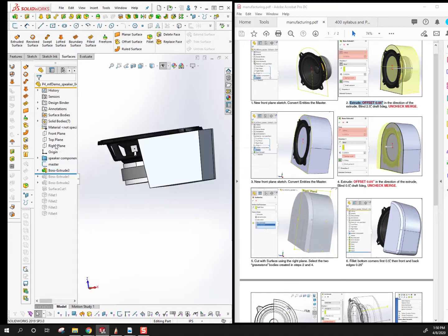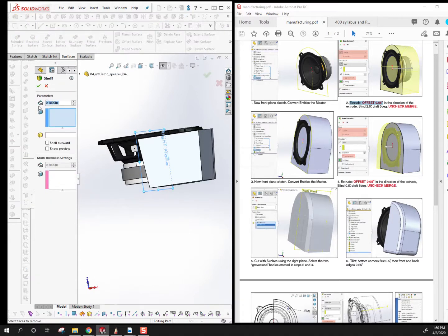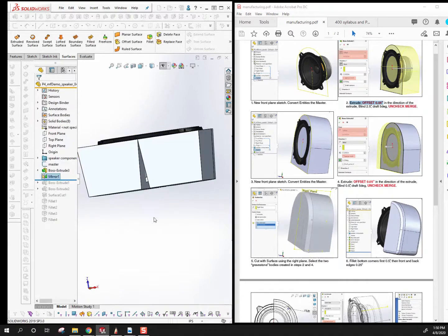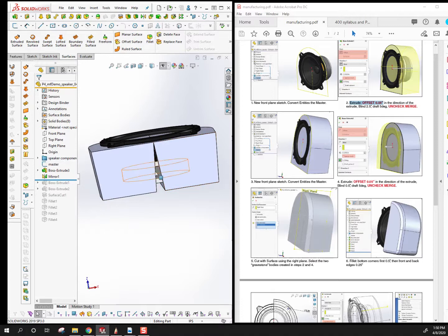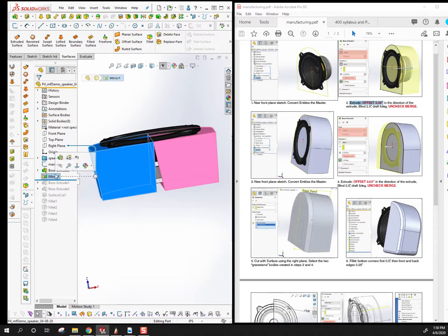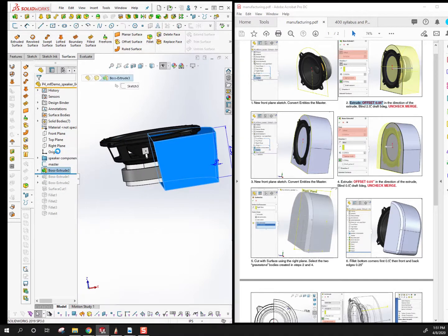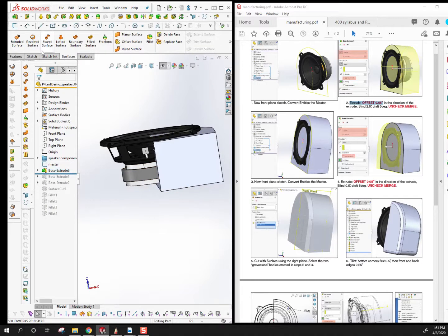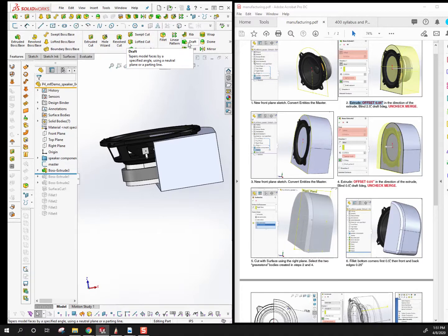So now if I continue with my build and I get to the end of my tree and I go to mirror this, oops, not shell, sorry, I go to mirror it. You can see that there would be an error in the mirror because of that draft. For what it's worth, if you want to build in this way that I have shown here, it's better to not have this draft be part of the extrude feature. It's good to know, or I would like you to know, that there is actually a draft feature command that acts independent of the extrusion.